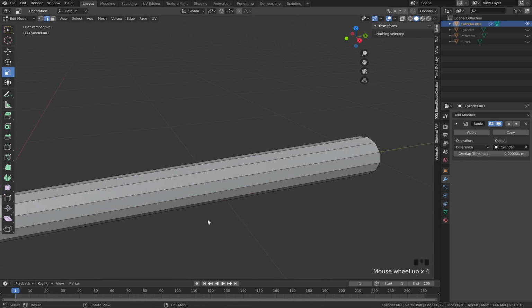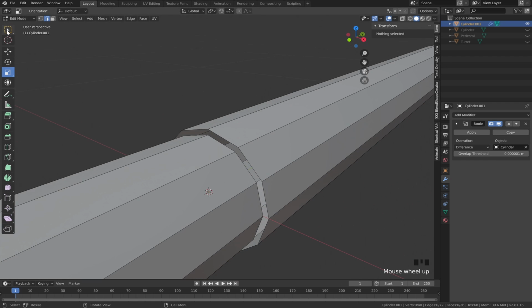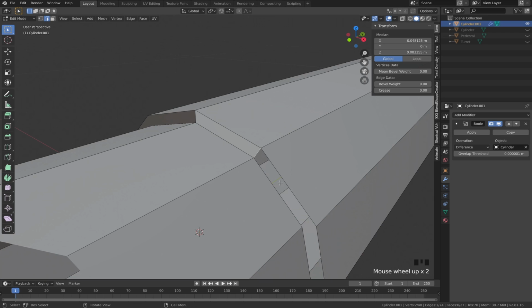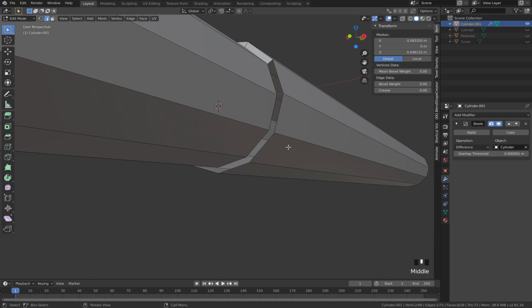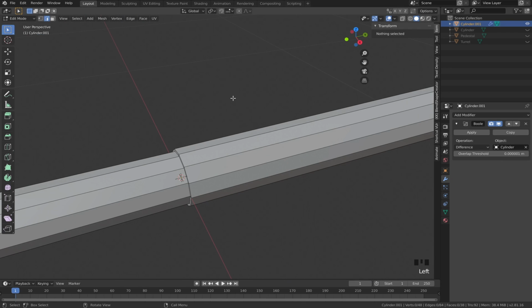All right. Now we also want to fix this. There's currently a hole in the model, so let's select this and this and press F. F would create a new face, but we don't want to keep going like this all the time. Select this face, this edge right here, just press F and see how it automatically does that? Now hold F and bam, it does it for you. No need to go through all the effort of selecting edge, face, edge, face.